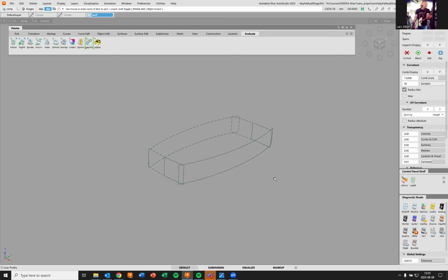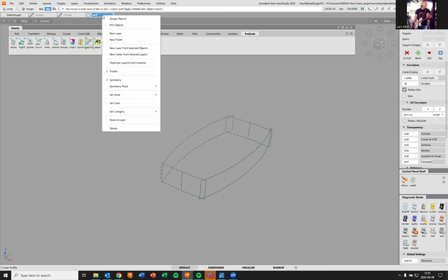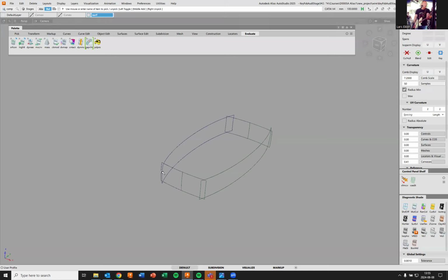Once you're finished and happy with the results, you can go ahead and create this geometry using, again, right click on the layer and symmetry plane, create symmetric geometry. It goes then from a ghost image to actual geometry. So if I hit that, I actually create the geometry. But we don't want that yet, so I'm going to delete that once again. So, and stop right there.